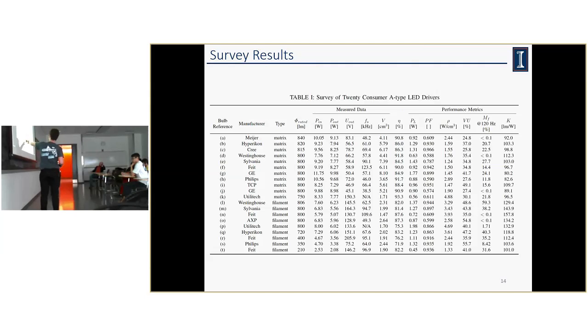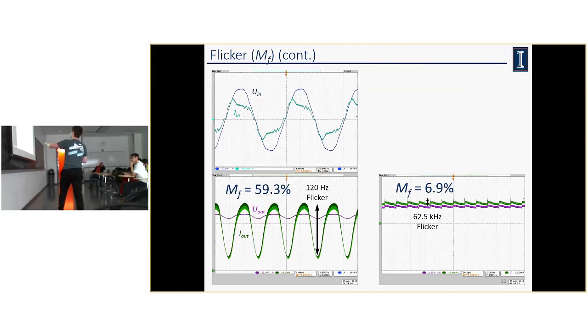Because at different points of the line, you either have to step up or step down. Some of these, like this one, is 200 volts output. I believe that's some type of boost converter. But all the other ones are buck boost, because this voltage is dependent on how many LEDs they put in a string. You can imagine in a company, you have all the different groups communicating with each other.